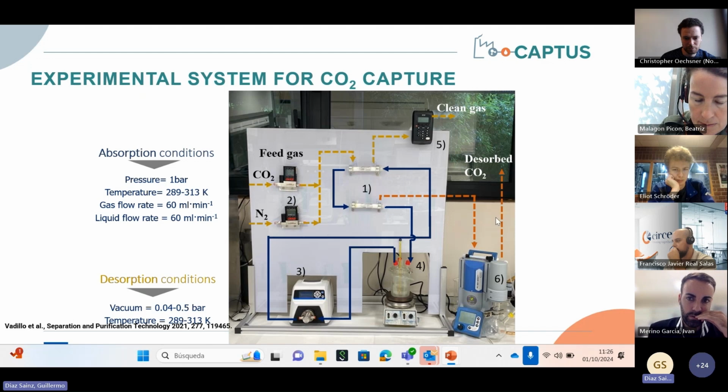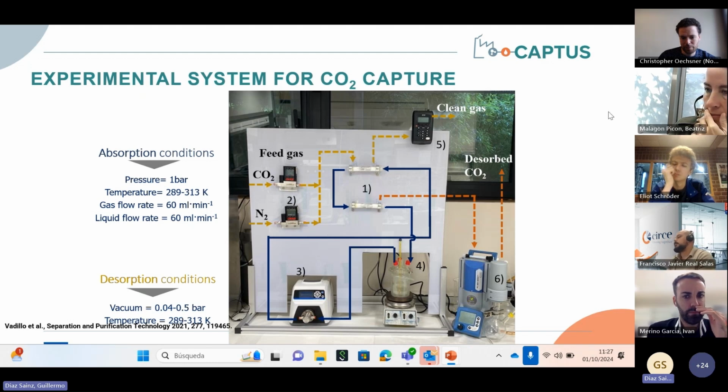The gas mixture was introduced through the cell side of the absorption module in a counter current and nearly atmospheric pressure. The ionic liquid was recirculated in a closed loop from a tank and through the fibers of the modules at a constant flow rate. It's very important here to fix the flow rates of both liquid and gas in order to maintain the pressure gradient outside and inside of the fibers.